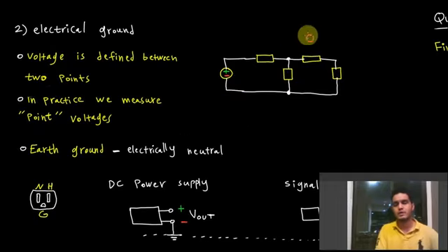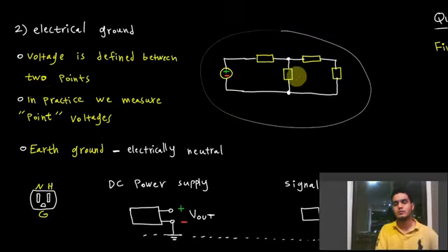If I were to look at this generic circuit here, I would need to use my digital multimeter or some other device that I measure voltages with and go across each element and probe it and look at what voltage I would get. In reality though, this is called the floating voltage. This is called a floating device right now. There's currents flowing here, but this device is just sitting on a plane by itself. There's no reference to any other locations or other voltages.